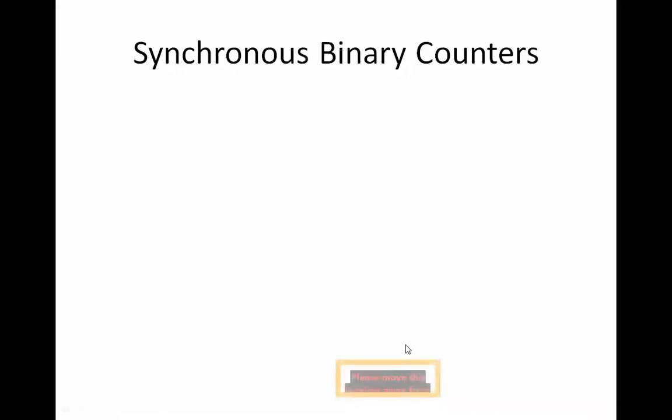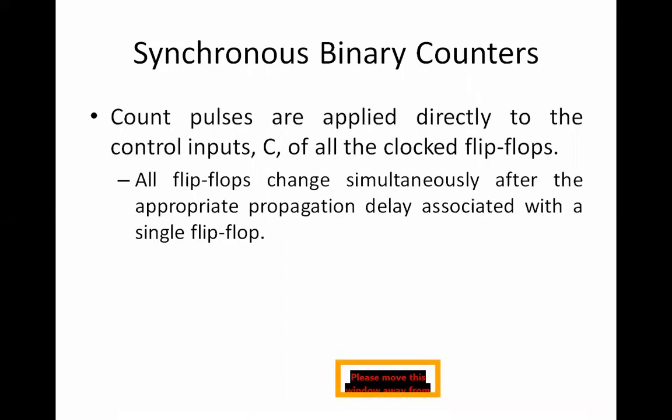Which is continuous, good, and it is also connected to a clock, right? The changes in the clock happen simultaneously. Count pulses are applied directly to the control inputs C of all the clock flip-flops. All flip-flops change simultaneously after the appropriate propagation delay associated with a single flip-flop.